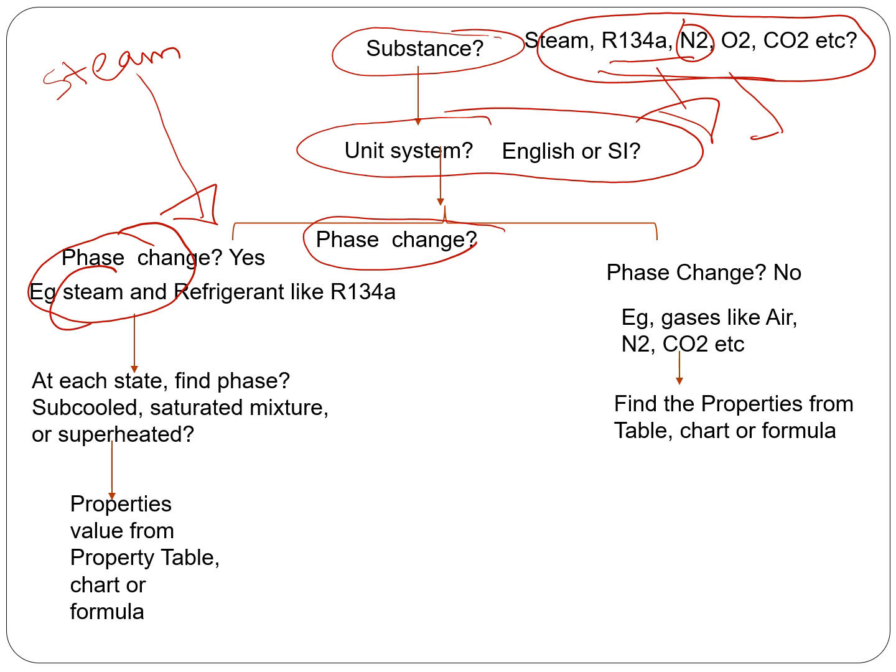So for steam and refrigeration, you have different phases. If that is the case, you need to figure out where it lies, whether it's subcooled, a saturated mixture, or superheated, and then find the property accordingly.